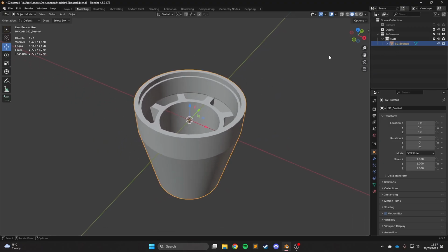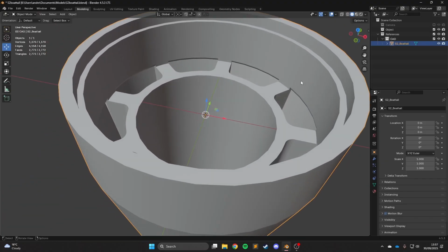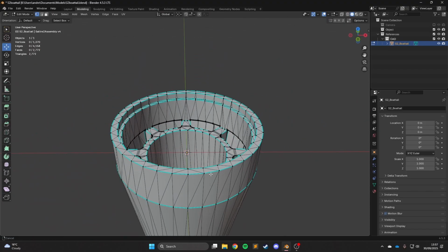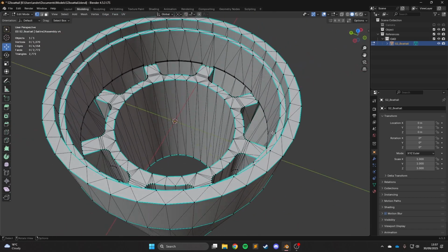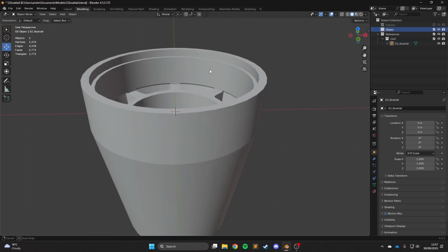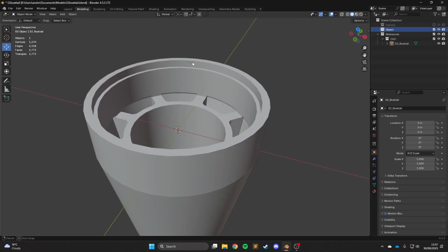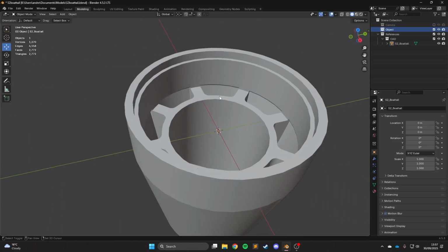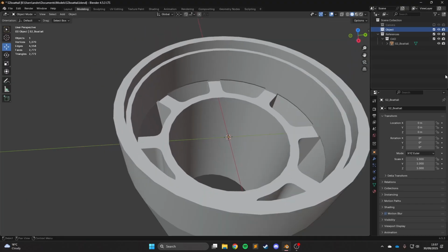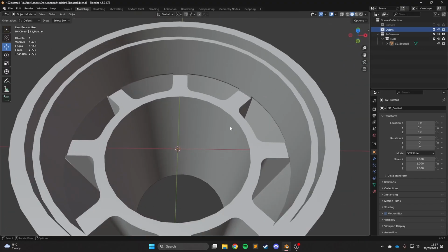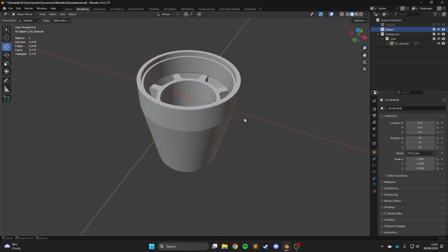So we've got the CAD file just directly imported, and because it's directly imported from CAD, all the dimensions are correct. It's essentially dimension perfect. The goal of this is to remodel it in Blender and make it slightly imperfect, so we're going to have some slight rounding on the edges. We're going to have better topology so we can use all our modifiers and all our nice materials on it. I'm just going to show you how I would go about solving this kind of problem in Blender.